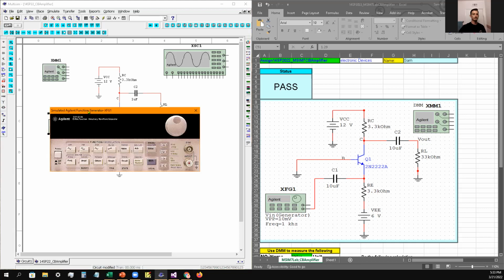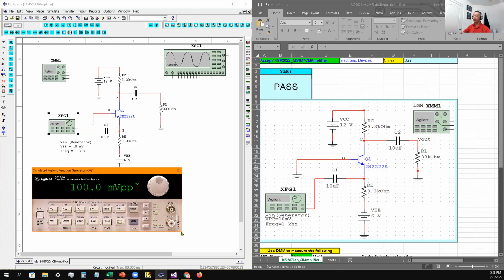Now I turn the power on, and it would show 100. So now I just use my hand and go to my keyboard and press 0, and that zeroes out the whole thing. And then you want to use this one to move the cursor to the right. So 1, 2, and right there would represent 0.01 volt peak to peak. That's the same thing as 10 millivolts.